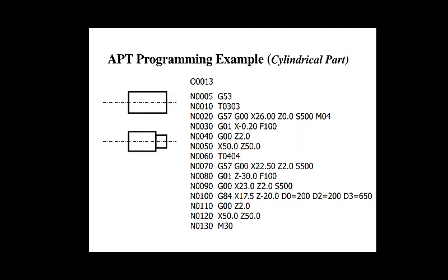That means in this rapid movement there is no cutting. So we are going to set the working zero point at X26, as diameter 13 from zero, and Z0 is the Z location. But here, let us finish this block. S500, that is spindle speed is 500 rpm.